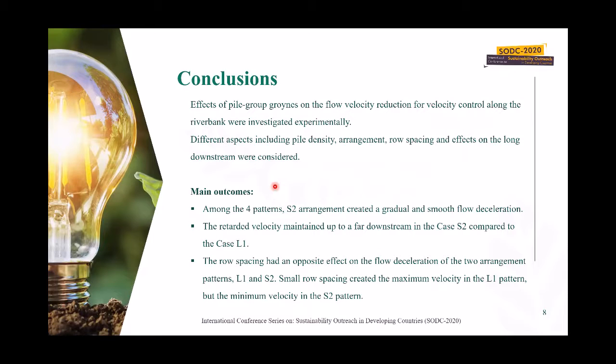Among the 4 patterns, S2 arrangement created a gradual and smooth flow deceleration, which is the optimum pile arrangement for the pile group groynes. It also has some other favorable features, like the retarded velocity maintained up to 4 downstream in the case S2 compared to the case L1.